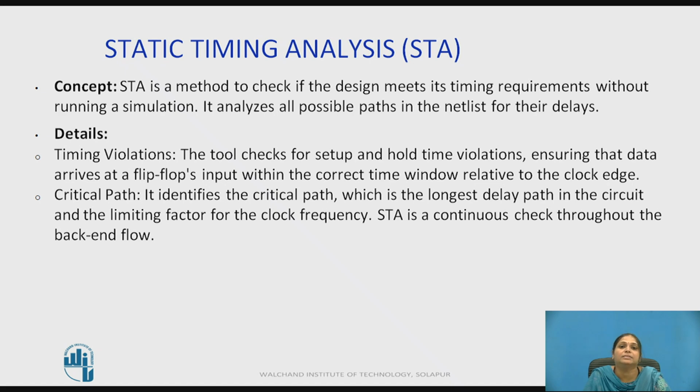It identifies the critical path, which is the longest delay path in the circuit and the limiting factor for the clock frequency. STA is a continuous check throughout the backend flow.